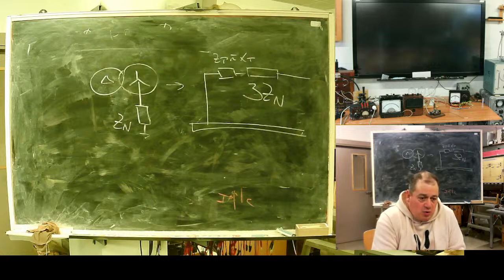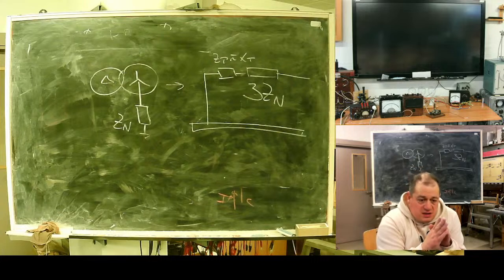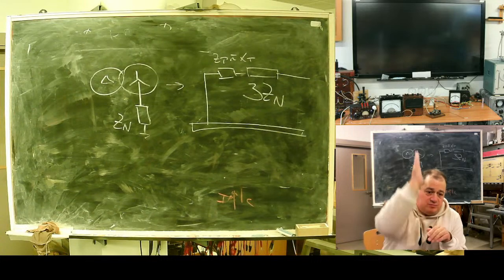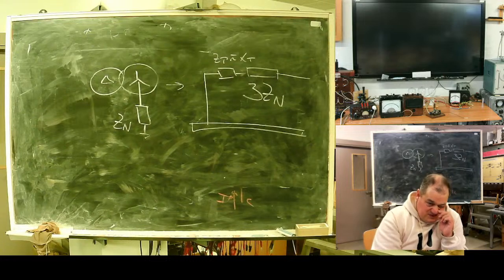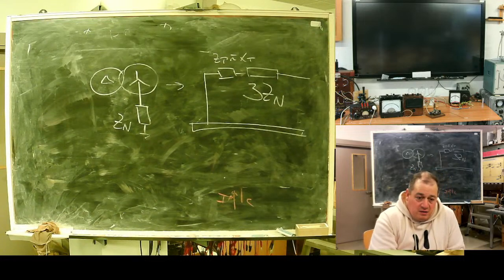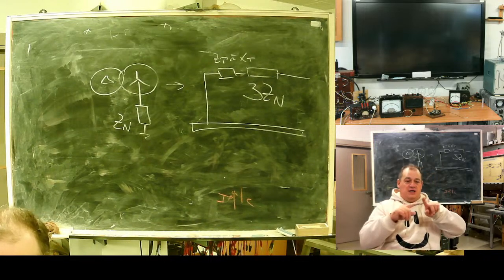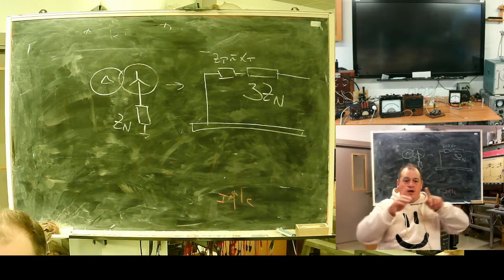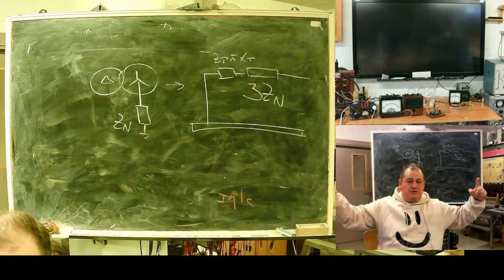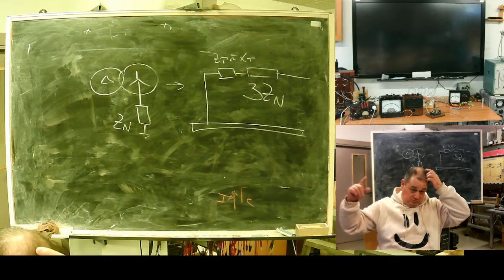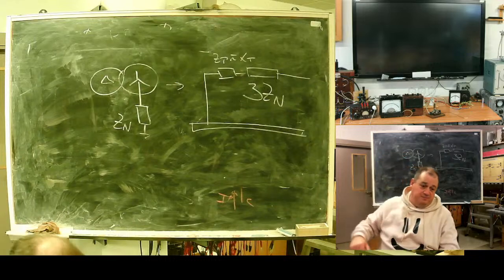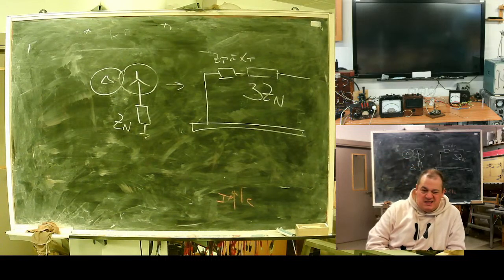And one more: the Carson model may not work if you have a line with each phase on its own pole, and the distance between phases is larger than the height. Be careful, there can be a problem. What else?